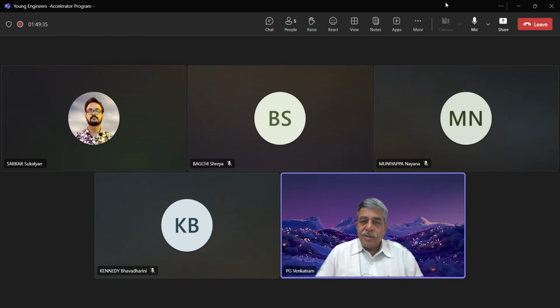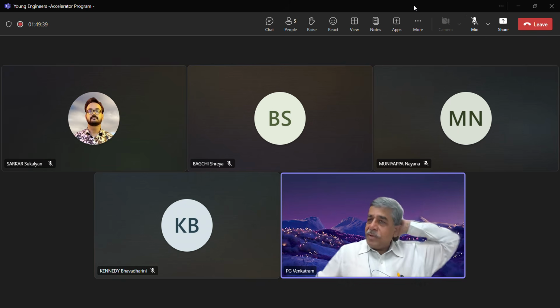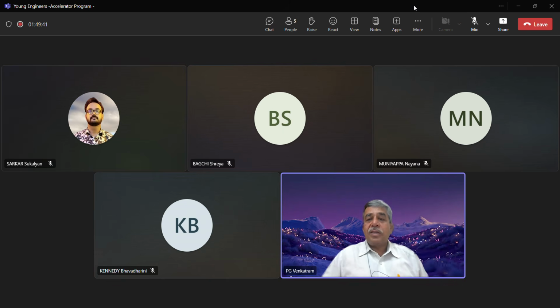Absolutely. So, to summarize, you have seen at the junction between superstructure and substructure what kinds of relative displacement take place. For each kind of relative displacement, some of it you can control and choose as you want. Depending upon what you allow and what you choose to restrict, you choose the type of bearing and the type of arrangement.